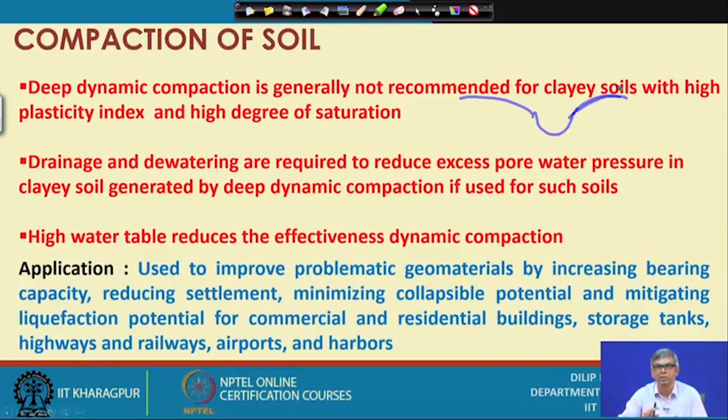When it is a little stronger soil, the grains will be pushed, come closer and get densified. But clay soil with high plasticity and high degree of saturation, this is ineffective.